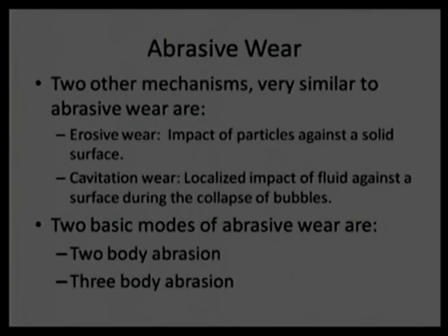This abrasive wear has a very common mechanism with erosive wear and cavitation wear. The only difference is that in abrasive wear we are talking about two solids, or about particles not with impingement, not with impact, but with sliding cum rolling motion.